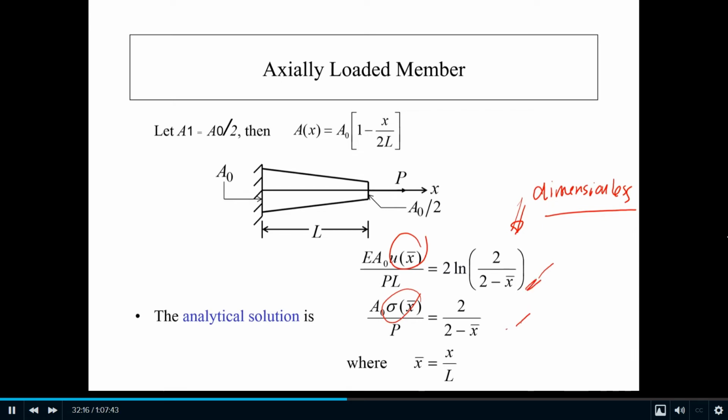A solution like this is a good way to solve for the analytical solution. But we're not going to talk about that here, because this is finite element. If you ask me, John, if we don't want to talk about it, why show me? This is important, because if the problem has an analytical solution, you should use it as a benchmark to check your FEM solution.